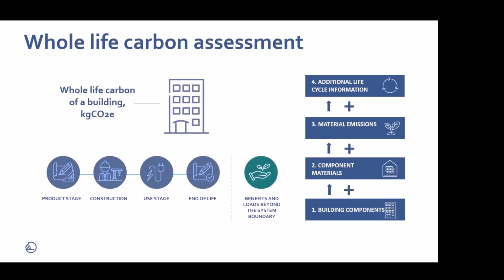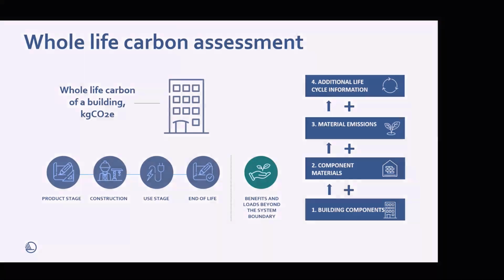The data in the building information model can be effectively employed in the calculation of materials carbon footprint if the building parts can be identified by the classification and properties in the model, correct material quantities can be retrieved, and product information is included in the model data, or the building components are labeled in such a way that the material properties can be retrieved from another source reliably.